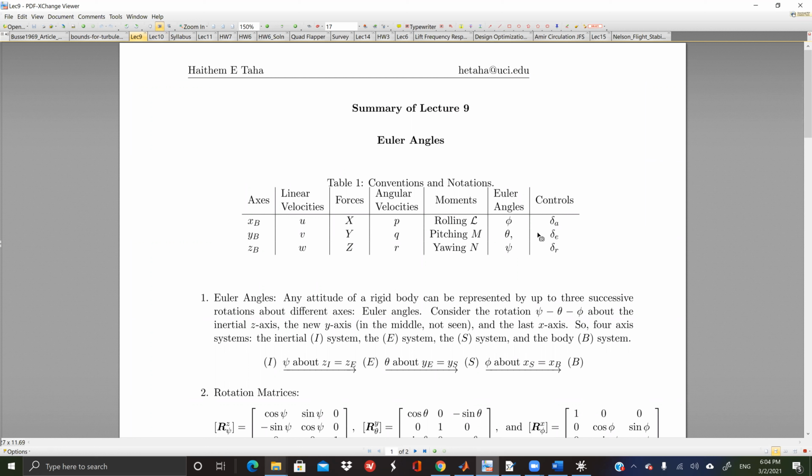You see this, right? So we need to know what is the stiffness and what is damping first. What is the stiffness? When you have a spring, what characterizes your spring? What is unique about the spring? Well, the spring gives you a restoring moment, and it's proportional to the displacement. So whenever you have an opposing force to the disturbance, and this force is proportional to displacement, it's a spring. And the same for the rotational version of it. Whenever you have a moment that is opposing the angle and it's proportional to the angle, then it's stiffness.